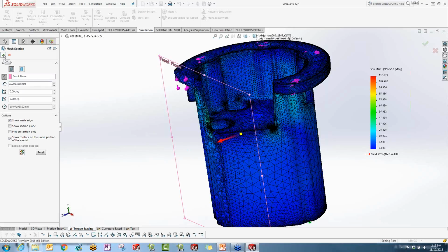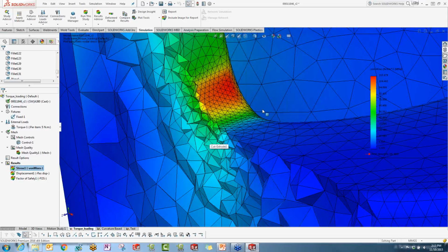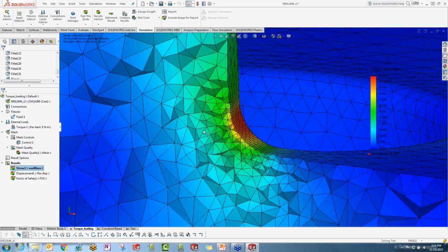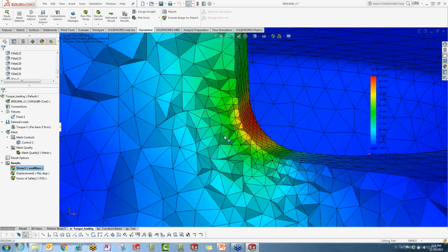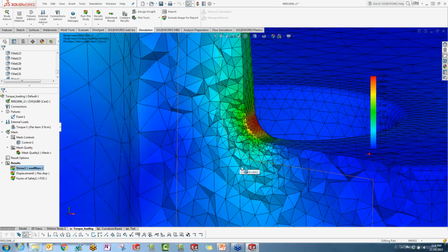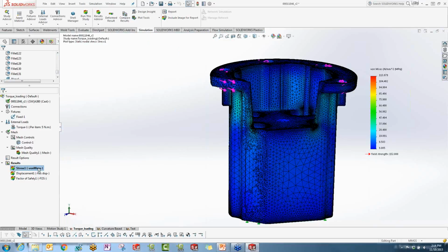All right. So if I save this view and zoom in, now I'm able to analyze and make sure that I have a sufficient number of elements in this high stress concentration area for me to actually get accurate information, accurate performance out of this model. That's method number 2, wherein you can go to your section clipping plot and turn on mesh sectioning.